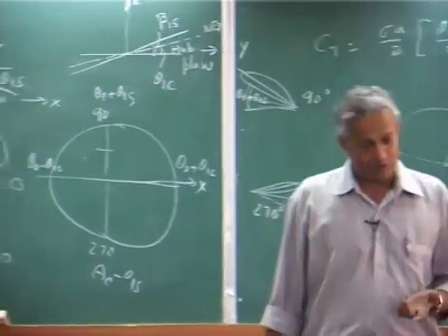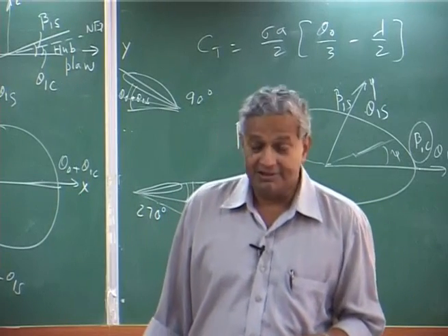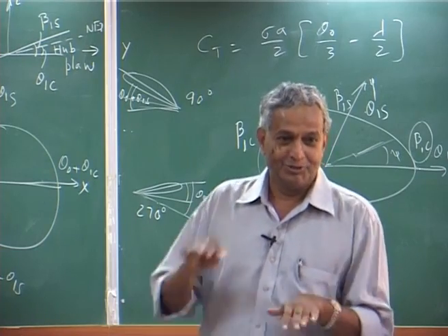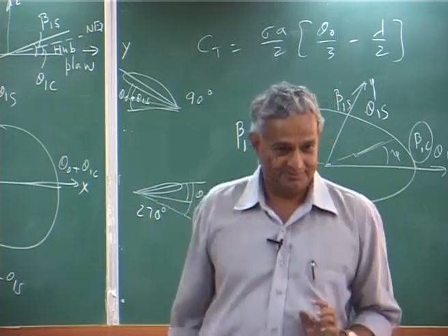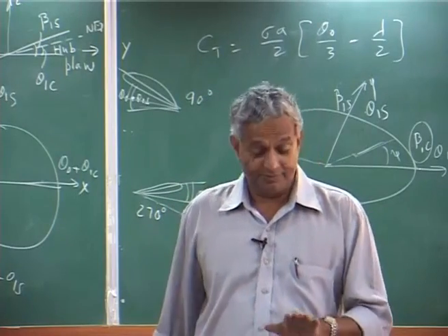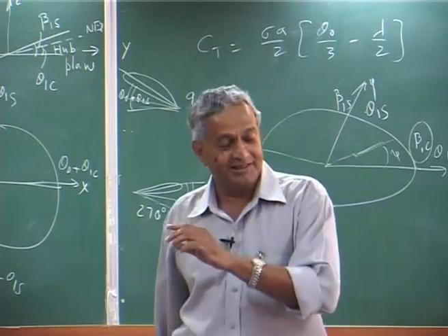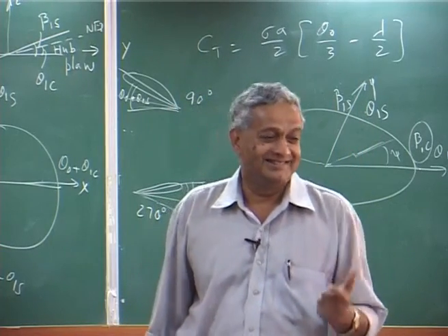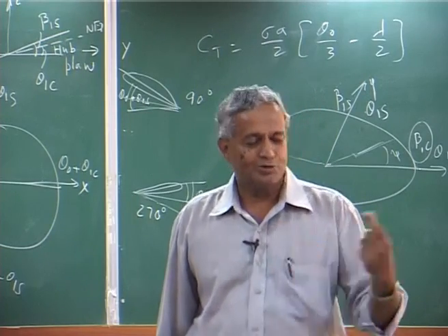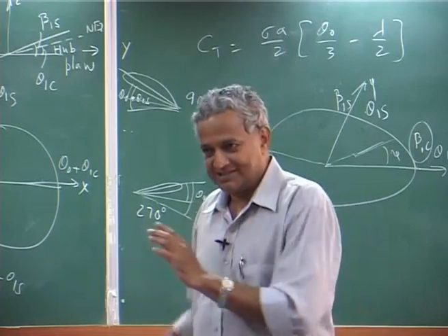Okay. Now, the question is, you can ask, what is the time lag between his input and that tilt? If there is a time lag, then the pilot will give an input, but the response will come slowly. That part we will study, because the flap is very quick. It happens within almost a quarter of a revolution, which is substantial. We will do the time constant and the other things.